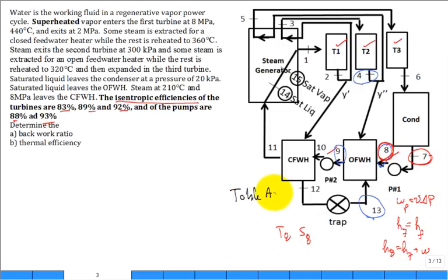Table A5, which has a table of compressed liquids. That's what got me excited about your answer. You're saying, hey, it's compressed liquid. There's a table of properties, compressed liquid. I know 2 independent intensive properties. In theory, I can get the other ones. So what 2 independent intensive properties for state 8 do I know after a little bit of work?